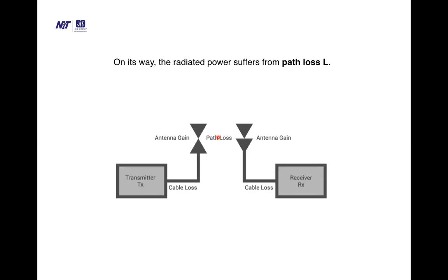So the path loss component is coming here. Whatever signal we are transmitting, that full signal is not coming to the receiver, and whatever signal is coming should be sufficient so that it can produce some intelligible meaning to the receiver. That is the important part, because if the signal is lost on the way, then there is no meaning of this system at all. So this study is very important for understanding total satellite link design.